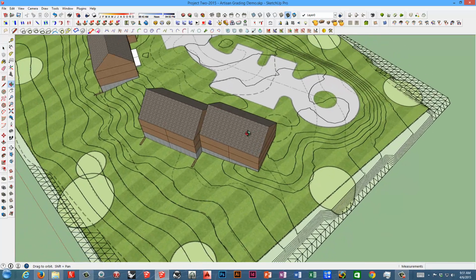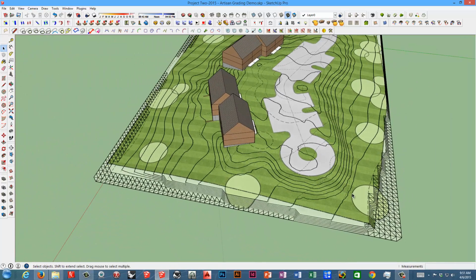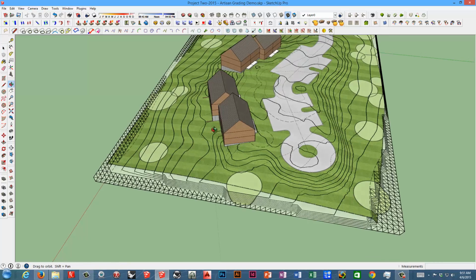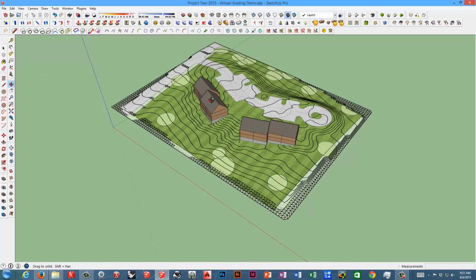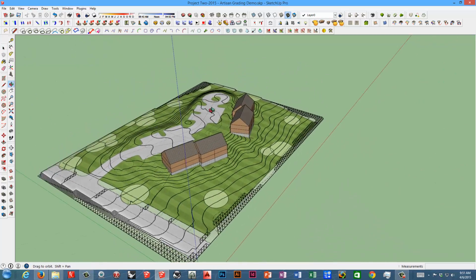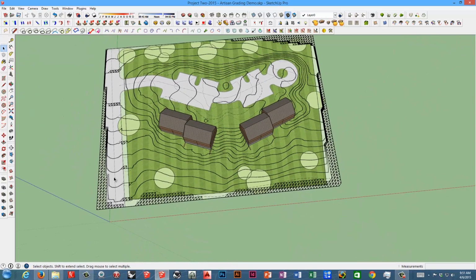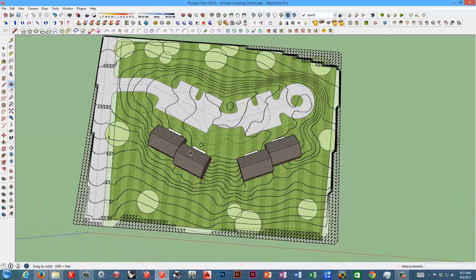So you can see whether your contours are pushing too close to the existing vegetation and whether that would be an issue or not. Yeah, there's some little anomalies with the grids and everything on the side, but the fact is that you can actually do a pretty good grading job to get an idea. Maybe you decide, well, this is looking fairly flat through here, but maybe a little too steep at the intersection, so I'd rather push this up and have it a little steeper in here and a little flatter where I reach the intersection.